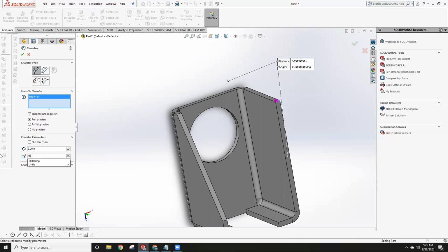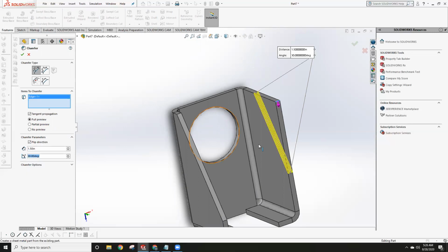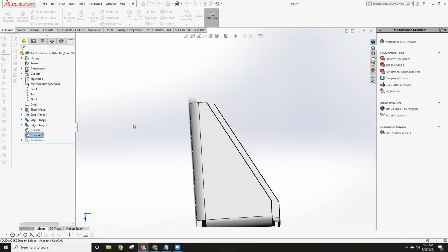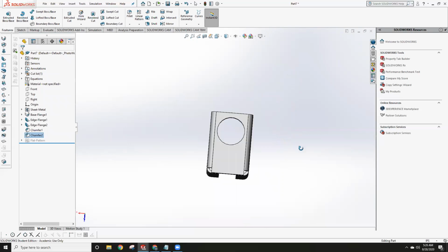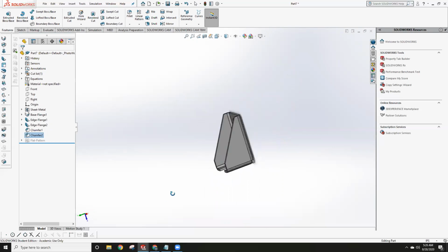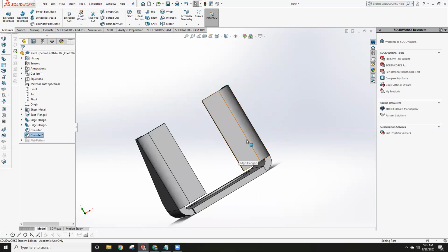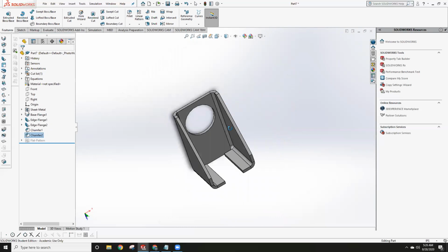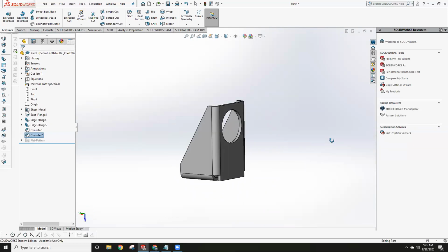Then we'll have to change this because it does a weird thing. Oh, and then we'll have to do like 1.5. Oh, no, wait, we'll do flip direction. So we're doing 30. Then we're going down 2 inches. Yep, cool, great, wonderful. Simple enough. And then if you were actually making this to serve a purpose, down here you would put some holes for rivets or bolts. I would recommend using rivets, especially for something like a chassis.